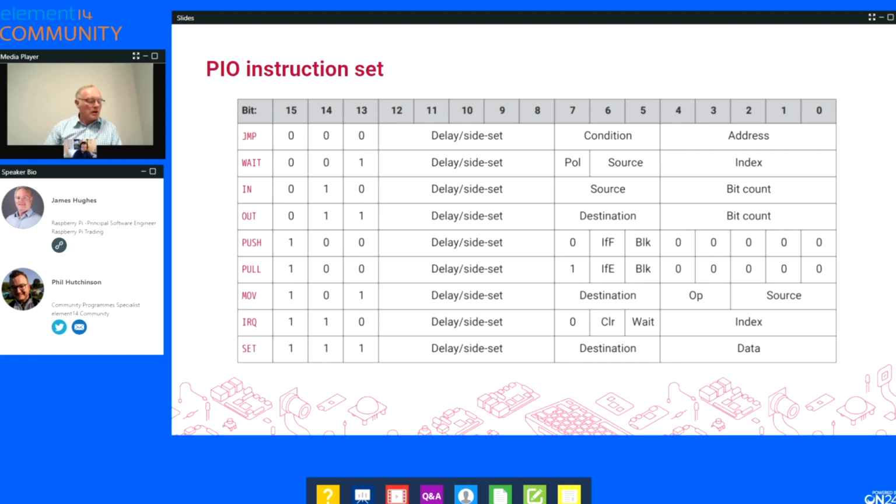So there are some clock dividers in there in the PIO as well. Generally, these processors run much faster than your communication system might want to run. So we can divide out the clocks, very accurate clock dividers, to make sure that if your processor is running at 125 megahertz, actually the PIO divides itself out and can run much more slowly for the slower communication protocols. This is a 16-bit integer, 8-bit fractional value, so it can actually divide out extremely accurately.